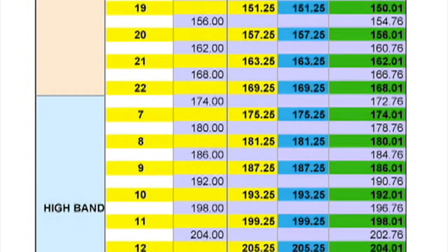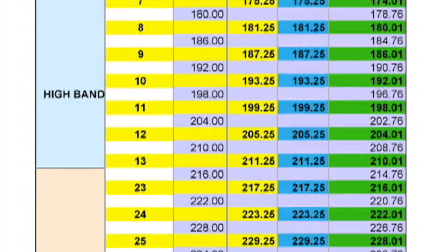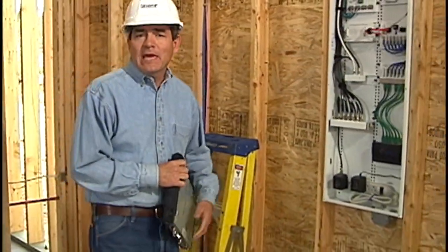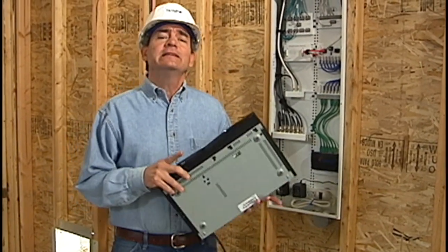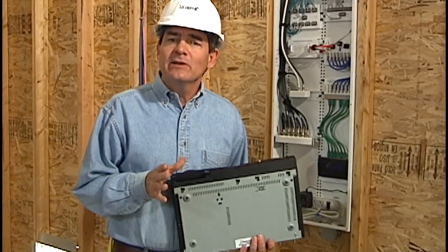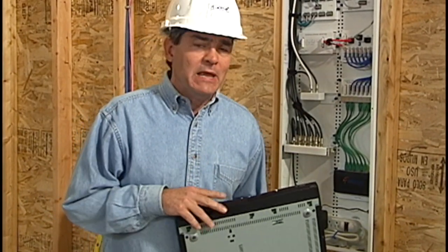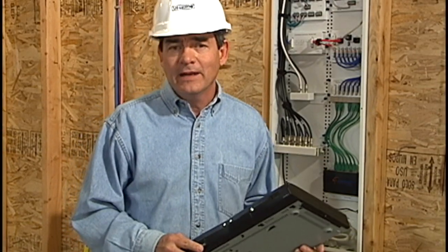Cable companies were required to begin using the EIA standard frequencies prior to 2000. By using digital compression techniques, cable companies can squeeze 6, 8, or more digitized NTSC channels into a single 6 MHz channel space, greatly expanding their potential channel capacity. But it requires a digital set-top box to convert those channels back into NTSC analog format.